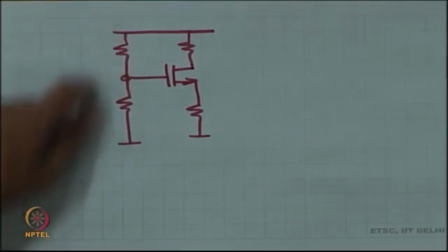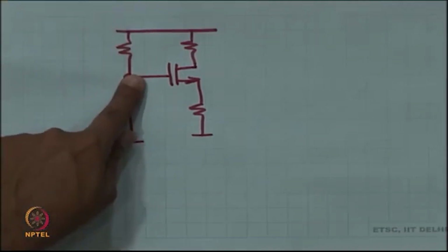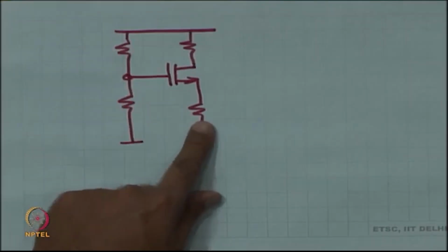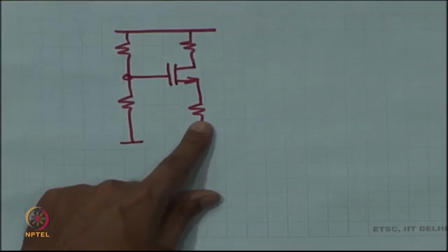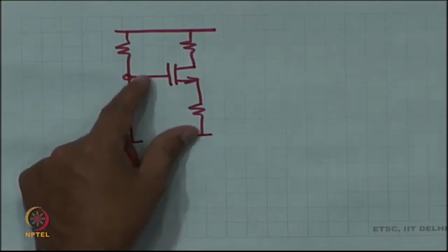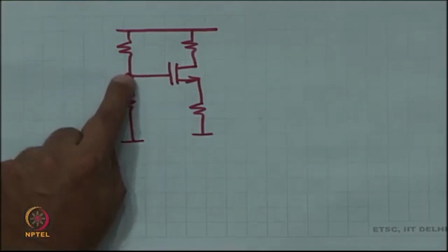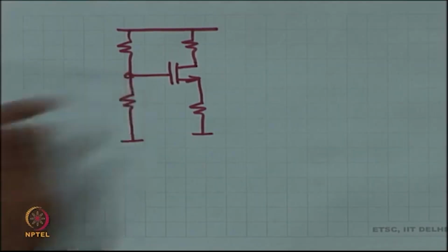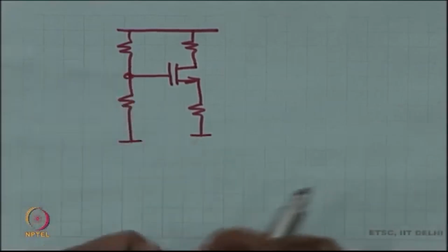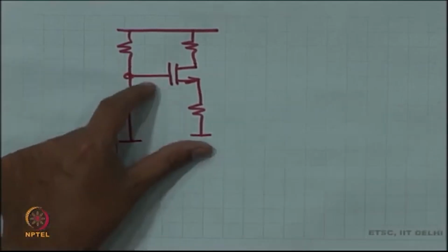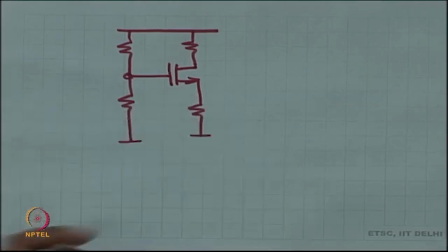So, this side you establish the voltage at the gate, and this resistor is important because otherwise the current is too sensitive to this voltage, to this precise voltage, the current becomes overly sensitive. To reduce the sensitivity, we place this resistor, and now you have got a much more stable DC operating point. Okay.